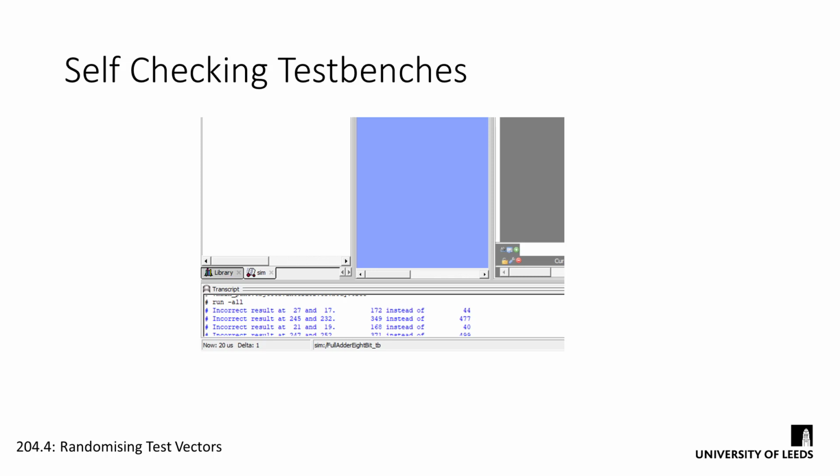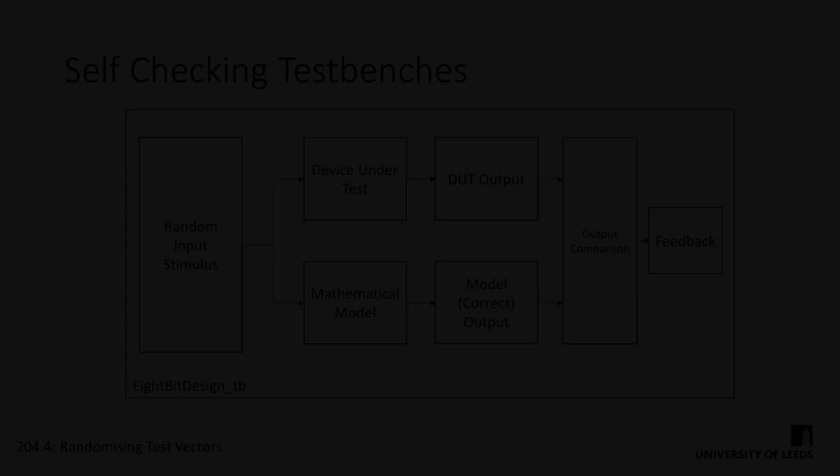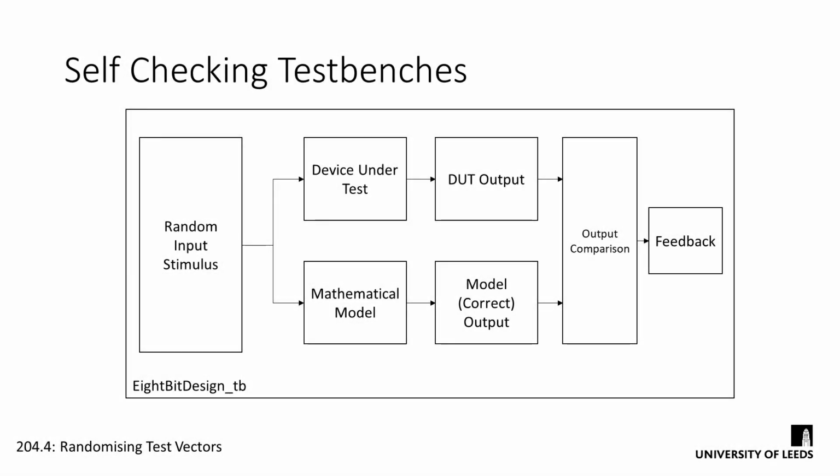Whilst this might be simple for an adder or multiplier, it would be a serious challenge for something like an HDMI driver or an FIR filter. And this is where the idea of the golden models that we discussed in the previous lab session come in. We can look at designing full software simulations for our devices under test so that we can compare them to the output of our digital designs. These rudimentary self-checking test benches allow us to increase the size and complexity of our designs without exponentially increasing the amount of time required to verify their functionality.